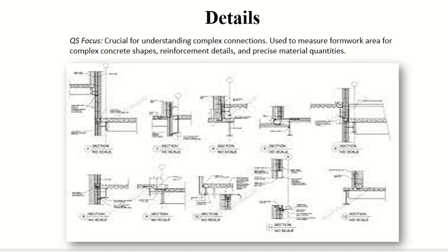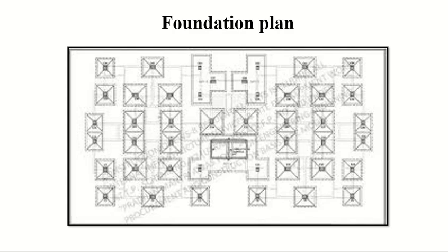And a very important part of the details, or the part on which we focus on these drawings, are the connections, okay? Where the beam is meeting the column is meeting the footing. These connections are focused in the details. And then we have the foundations. So you can have a foundation plan which tells you where are the foundations, how many are they, what are their sizes, and so on and so forth.